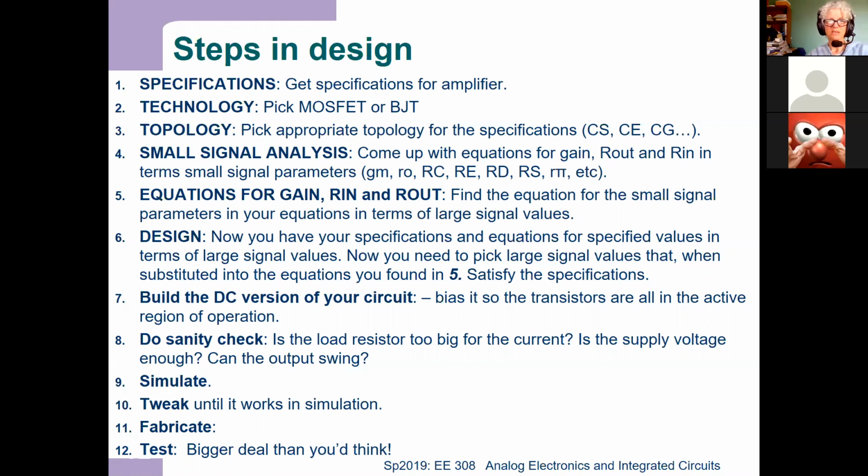I know that went by kind of quick. These steps are on the single transistor amplifier slides. When I say single transistor amplifier, if you look at a common emitter with an active load, you see 2 transistors there, but that is still considered a single transistor amplifier. It's just that the load is made out of a transistor too. Common source, common emitter, common collector, common drain, common base, common gate are all considered single transistor amplifiers, even if they have a second transistor somewhere in their circuit. Just on these first 4 steps, are there any questions?